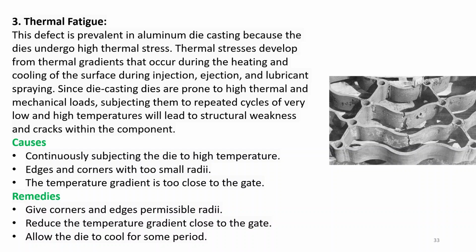Next question is thermal fatigue. This defect is prevalent in aluminum die casting because the dies undergo high thermal stress, and the thermal stress develops from the thermal gradients which occur during the heating and cooling of the surface during injection, ejection and lubricant spraying.